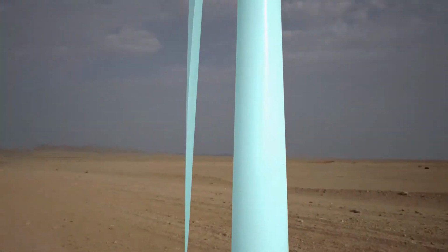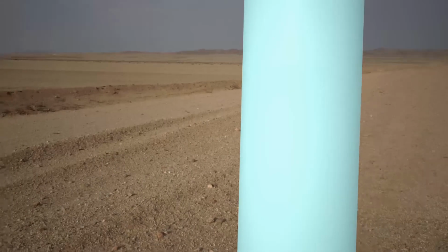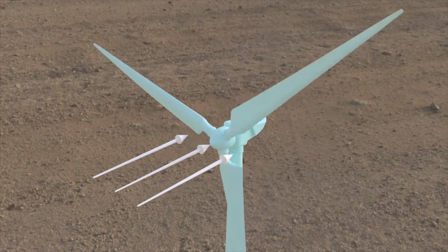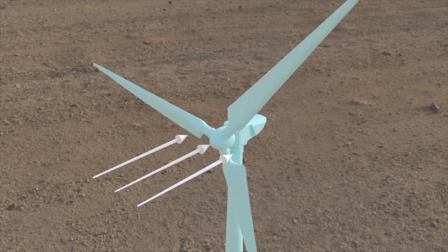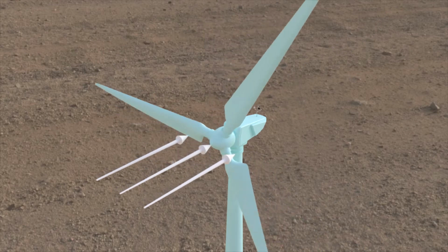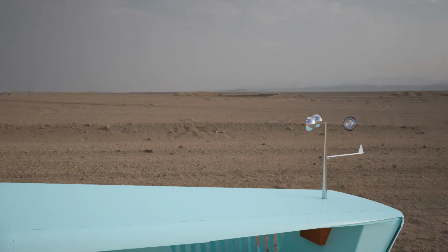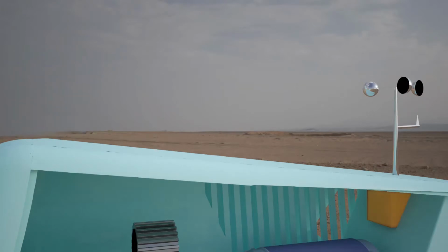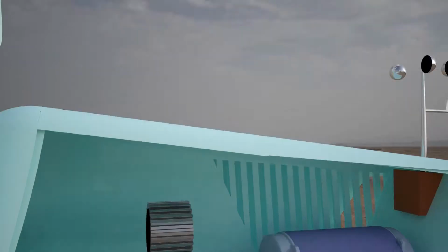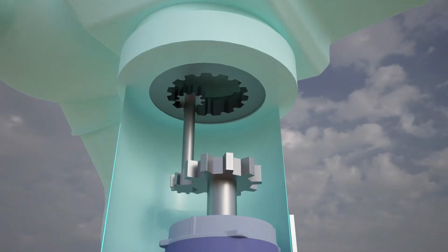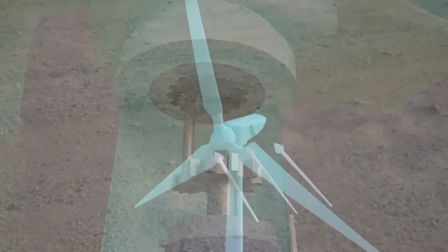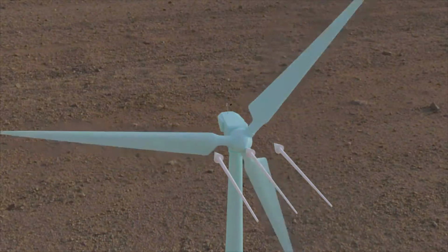Electricity produced from the generator passes through a cable towards the bottom of the tower where the step-up transformer is situated. The wind turbine should face toward the wind for maximum power generation, but the wind can change its direction at any time. An anemometer and wind vane are located on top of the nacelle. They measure the wind speed and direction. If there is any change in the wind direction, it sends it to the controller. The control system controls the yawing mechanism to rotate the nacelle with the help of the yaw motor, so the wind turbine can always align with the wind's direction.